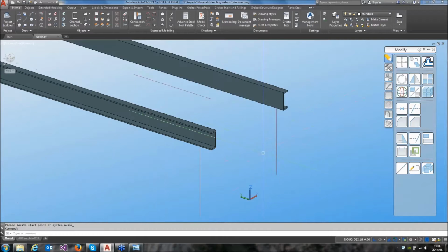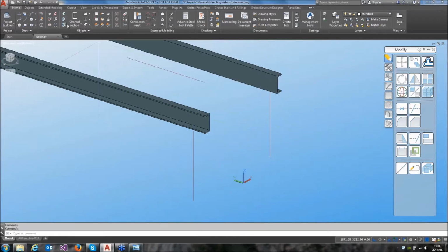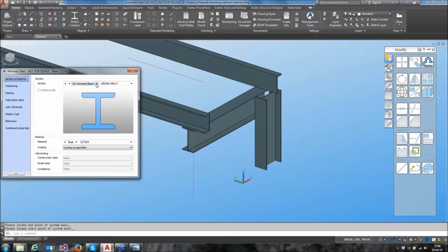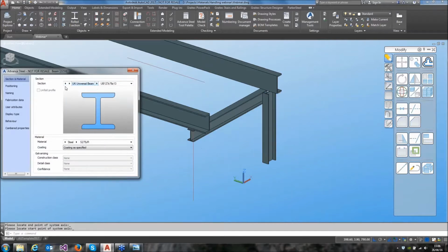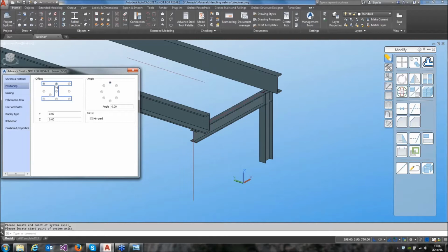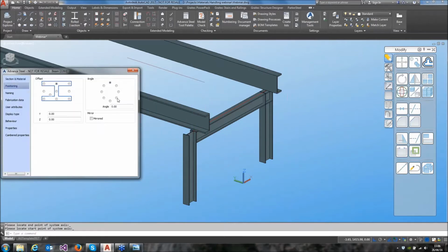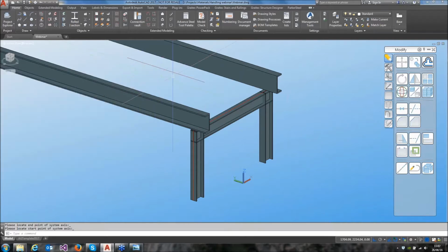We need some legs to hold that conveyor now, so I can use these lines with a couple of I-beams. They need to be small, so they're going to be the smallest one in the range, like so, and then go to the other side, and that one needs to be rotated so it's in the right place. Now I can put some joints on there.